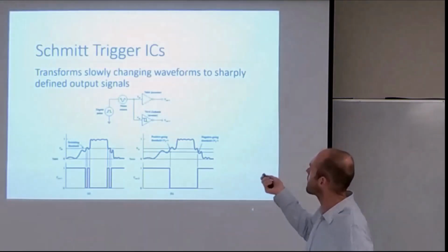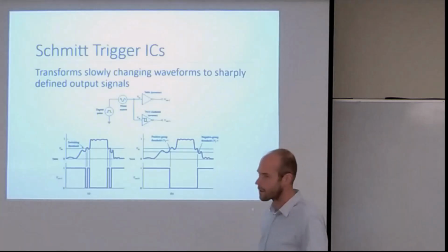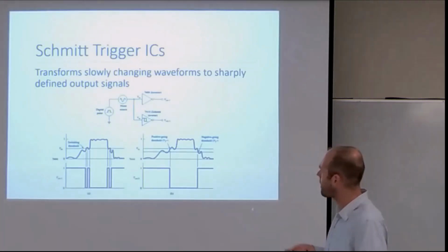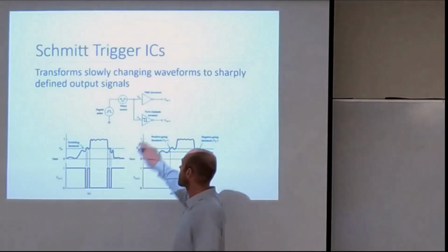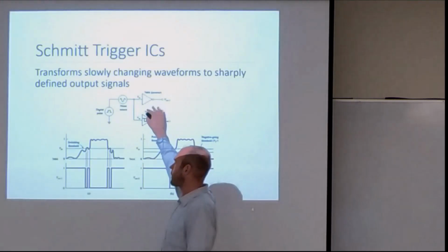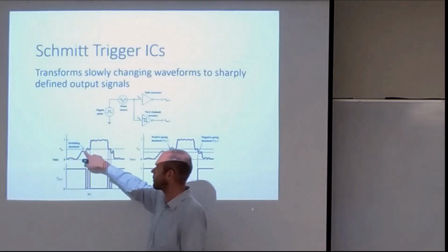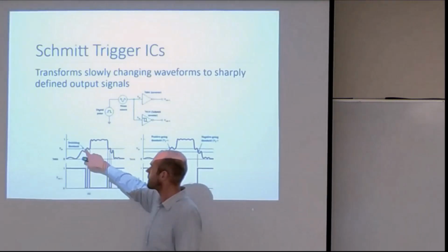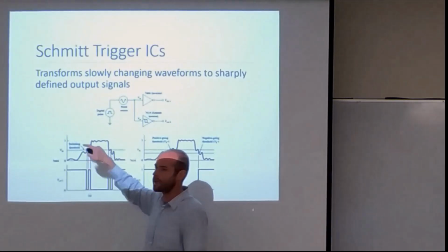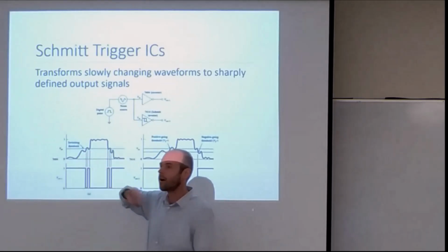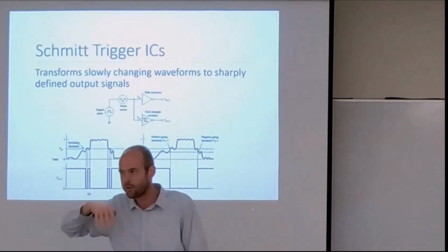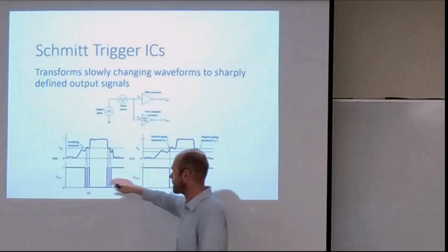Chapter 11 in your book, if you're following along. So first, the introduction of the Schmitt trigger. You may have run into this before, possibly not. If you send a noisy signal through a regular inverter, and the noise makes your signal go up and down, every time you cross above or below the threshold of the inverter, your output signal is going to flip.